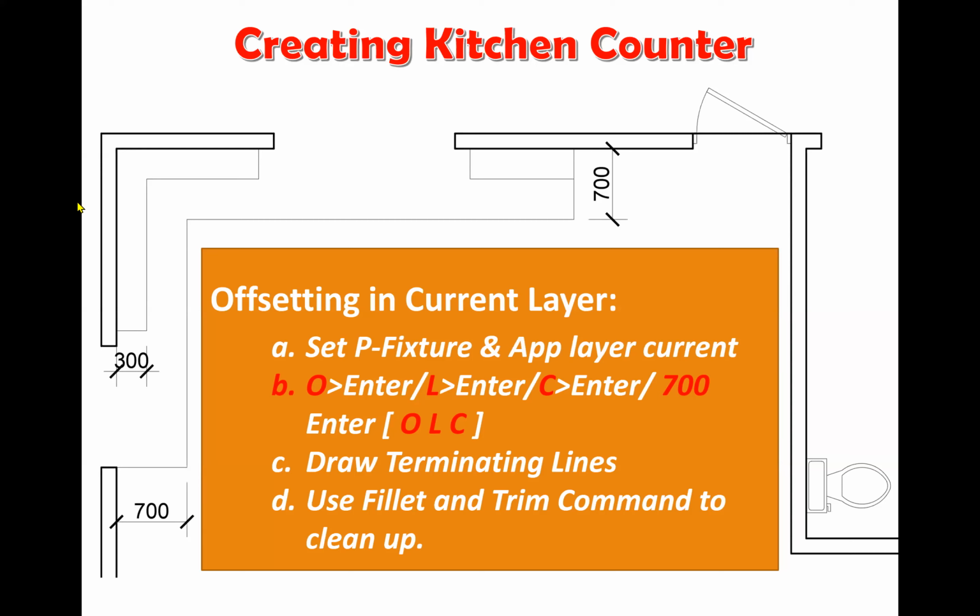Now, the distance that we're going to be working with for our cupboard is 700 millimeters. And cupboard, again, the width of the cupboards are standard width. The length, there's no determination. The length is based on the availability of space. So this length could be whatever you need it to be. But we are going to stop it basically about midway up this wall and stop it where the end of this window is.